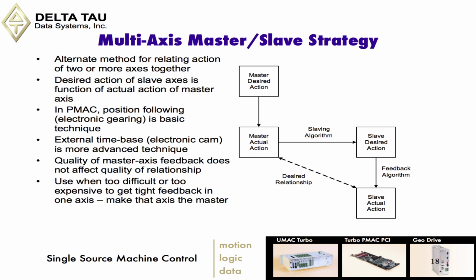Depending on when you use the master-slave or the external time-based electronic camming for doing this coordination, it really depends on how well your feedback is compared to how difficult it's going to be to set up this kind of system, using master slaving compared to external time base.